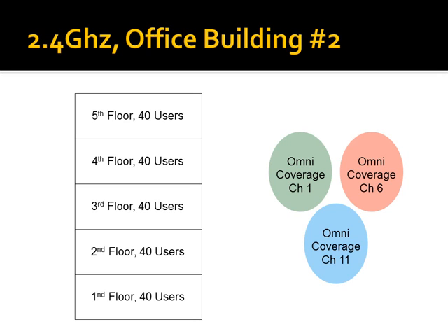So how much power do I start with? That's a radio choice. We don't have a lot of choice in that. We are legally, on almost all the frequencies you guys will use to do this, limited to a maximum of 1 watt. Typically, you're going to be using half a watt or even 1/10 of a watt. Most home APs use 1/10 of a watt. So your power can only do so much. Your real control is choosing the antenna and choosing the pattern that accomplishes what you need. So be sure you think through that as you look at problems.